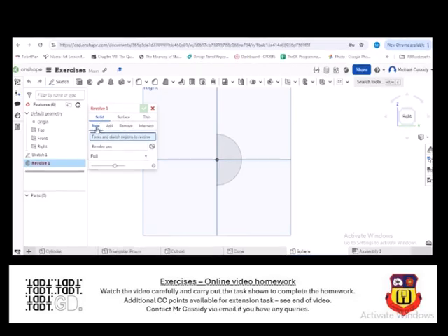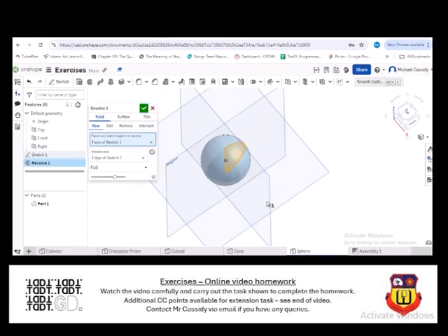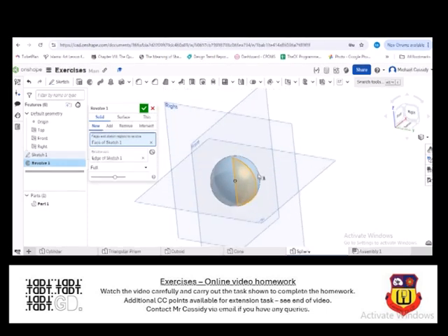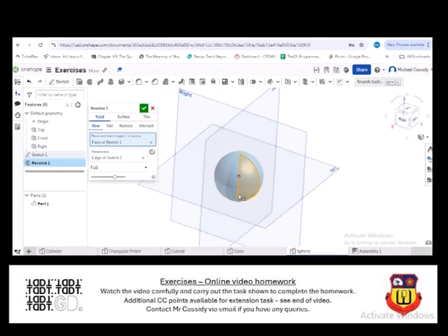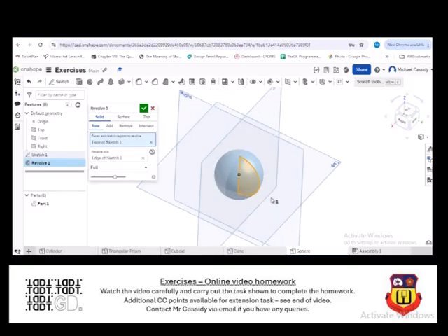So it's on solid, new. So it's again 2 pieces of information that it wants. So let's choose the revolve axis, which is going to be that central line. And then we're going to click on the faces and the sketch regions to revolve, which is our semicircle. And as soon as you click on that, it creates a sphere. Quite useful to see the original shape as well, because we can look at that and we can see how that's revolved through 360 degrees.